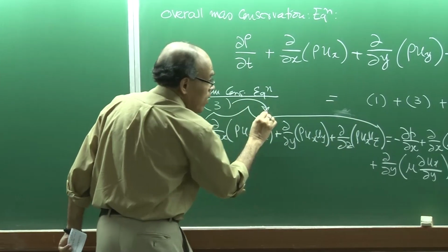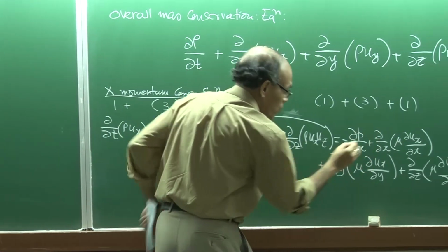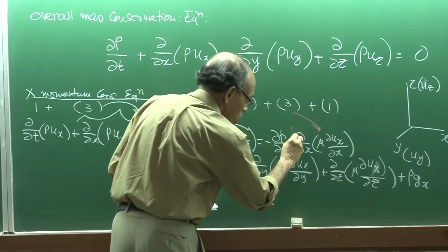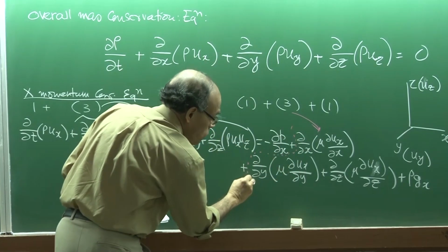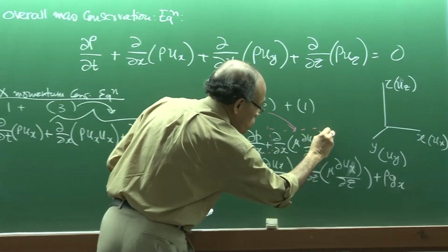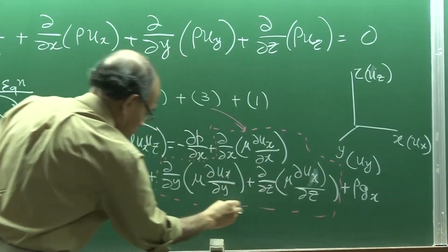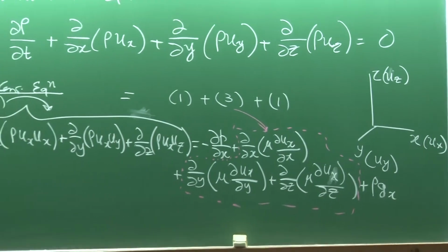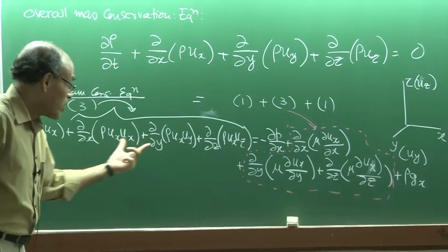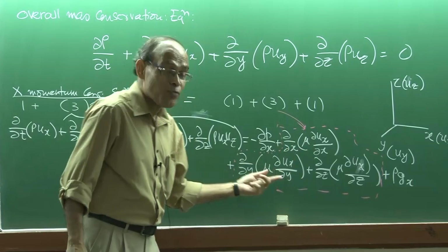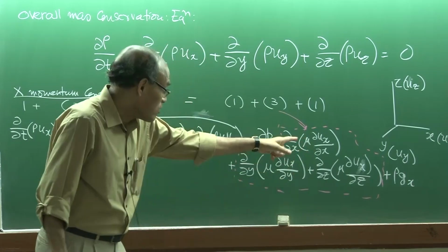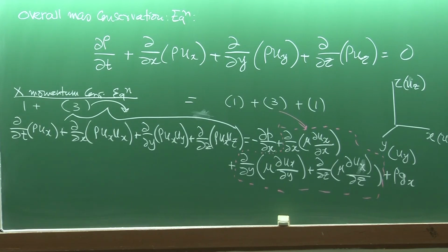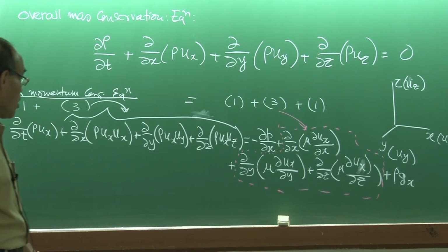These are the terms that I am talking about. In a three-dimensional problem, there are three convection and three diffusion terms, associated with the inertial forces and with the viscous forces. These are the terms which come because of the shearing stresses in the fluid, which I have explained to you in the context of the film flow problem.